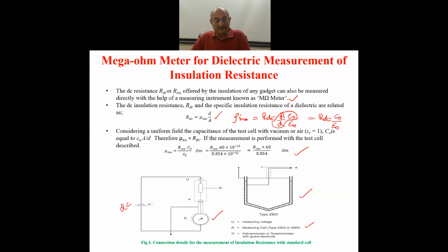So this is another important resistance instrument. Insulation resistance also gets adversely affected with the bad condition of the dielectric. The worst of all would be the moisture content in the dielectric, or humidity, or even the quality of the dielectric would affect the value of the insulation resistance.